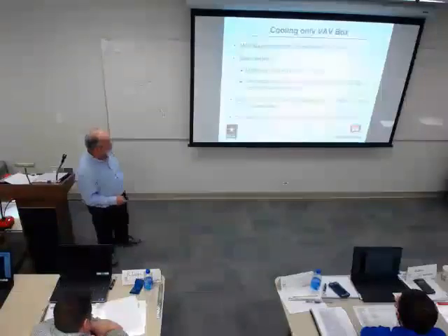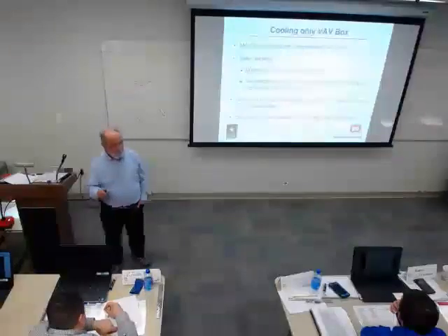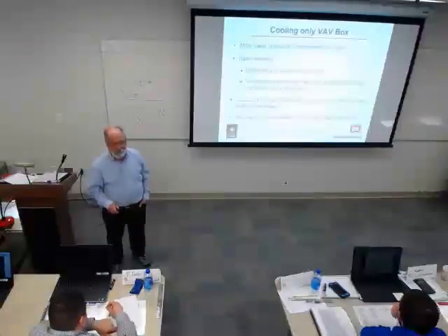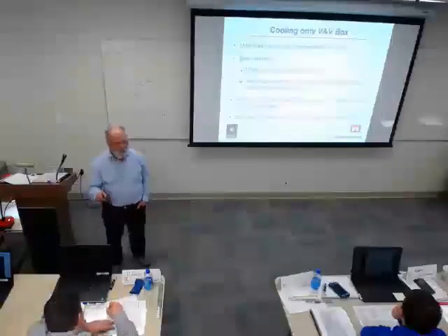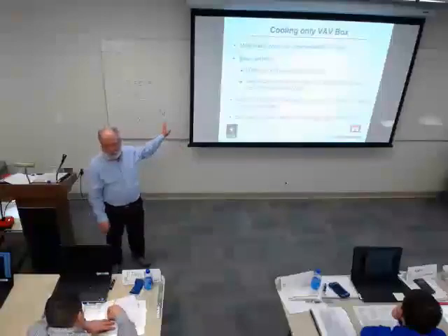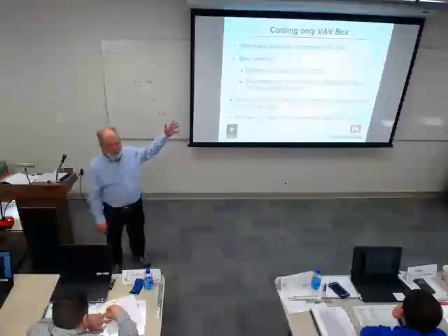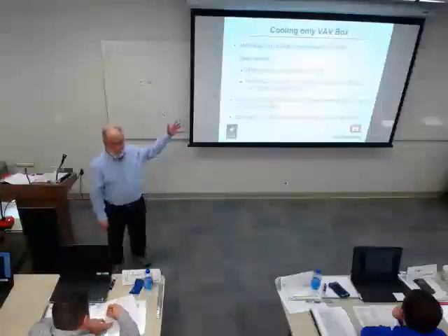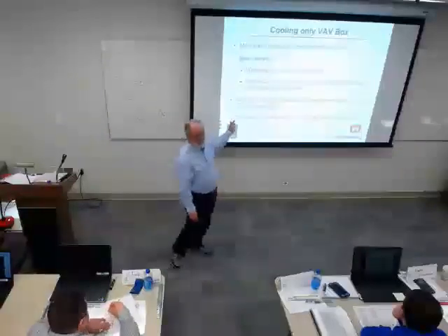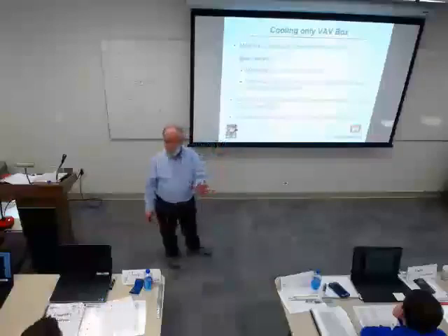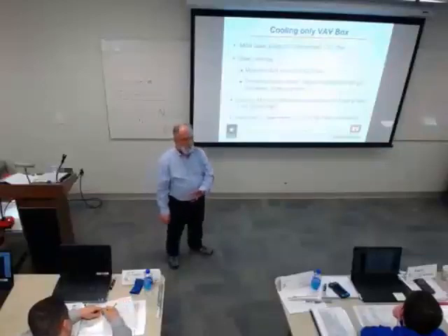Now, right here I need to mention something, and that is that during TAB, you need to check to be sure that that box knows what the duct dimensions are. Because very often the control guy will go through and put in the same size for everything. And this actually measures CFM into the system. Don't know why they do that, but they do. I guess because they're reading the need or something. At any rate, instead of just looking at the velocity of the room, it actually looks at cubic feet per minute into the room because it multiplies that velocity by the area, just like we did by hand a while ago. And so that will always be wrong and it'll cause you problems.